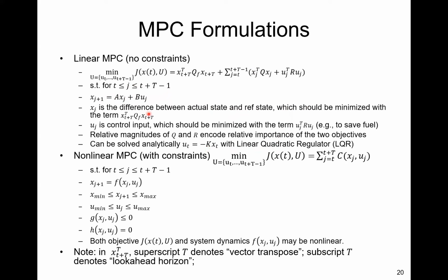You can solve this problem analytically by using the linear quadratic regulator method. So this is a proportional control. No, it's not. This x may be a vector of state and state derivative and so on. So this could be a PID controller. The K could be a vector of P, I, and D terms.